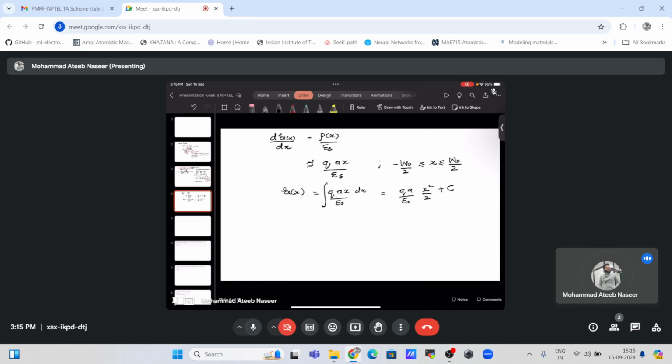Okay, now we know that the electric field at the depletion region edge has to be 0. That is, the electric field at the depletion region edge has to be 0. It has to terminate, because we know that the bulk of this material will be free from any kind of field. So this is a valid approximation.